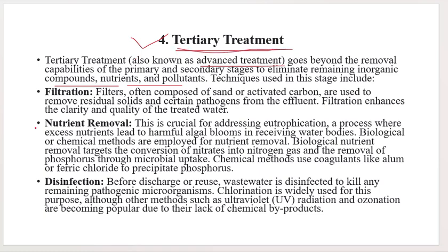Okay. So the first is filtration. Filters are often composed of sand and activated carbon, and are used to remove residual solids and certain pathogens from effluents. Might be bacteria or some other pathogens present in wastewater, that will be removed through filtration. Filtration enhances the clarity and quality of wastewater. Through this filtration process, we can get quality treated water.